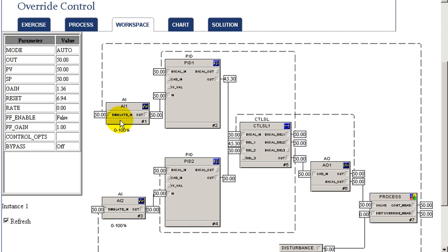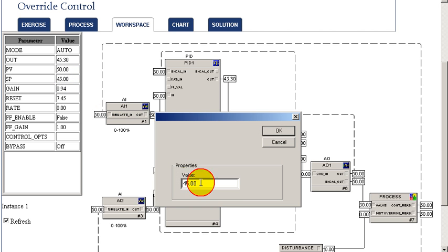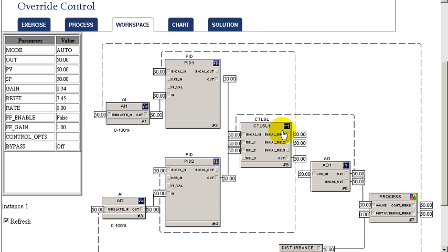In this workshop, we have the control set up where the override controller's set point is at the measured value. In the first part of our exercise, we're going to set the set point of our control parameter also to match our measured value coming in, 50%. And so under this condition, where both the override control and the primary control are at set point, you notice the output of both controllers match each other and are equal to the input to our process at that point. So under this condition, everything is balanced.